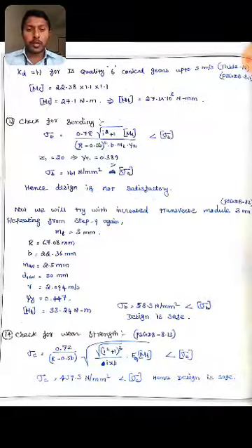So design MT is equal to 22.38 into 1.1 into 1.1. So design MT is equal to 27.1 Newton meter. To change into Newton mm, design MT is equal to 27.1 into 10 to the power of 3 Newton mm. Next, step 13, check for bending.